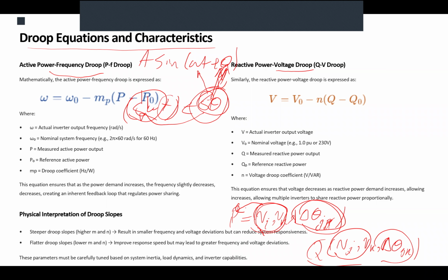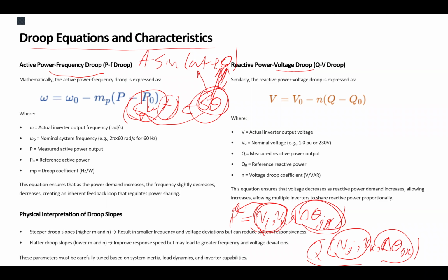So you can basically interpret the need for active power by quantifying it with a phase difference. Does that make sense? So now in droop control, we translate that phase difference into a frequency difference because they are basically the same. They are radians. We just wanted to make a mathematical transformation.